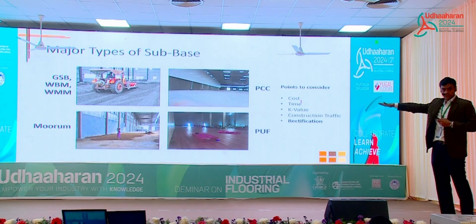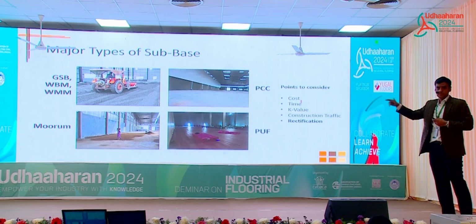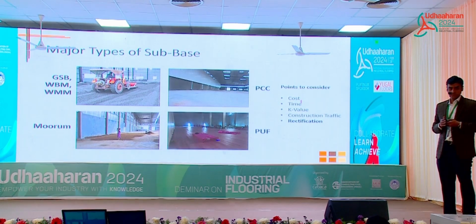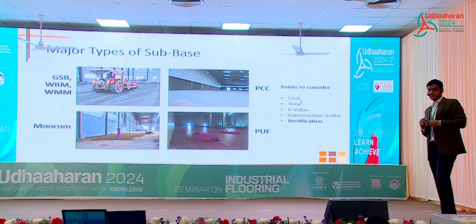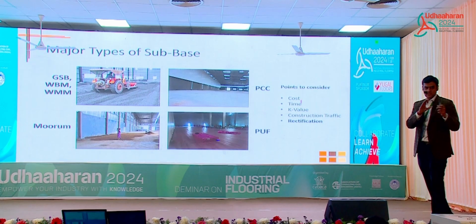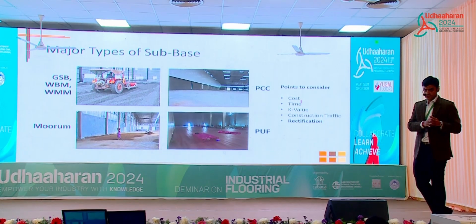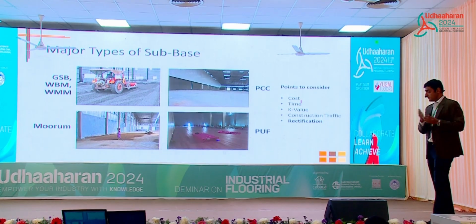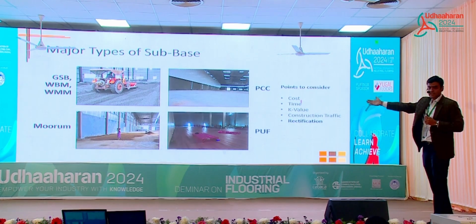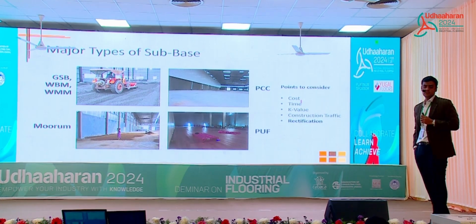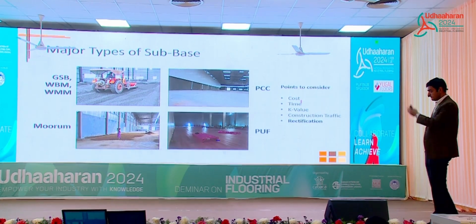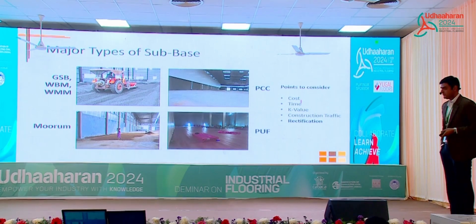Third is Muram. In Hyderabad, actually 90% of our projects we've done on Muram, because the quality of Muram there is excellent. So you should have that awareness. These materials are very, very city specific, so you need to know what is good there. In a place like Hyderabad, the GSB is really unnecessary for a warehouse project. We've done many projects just on Muram, very good quality.